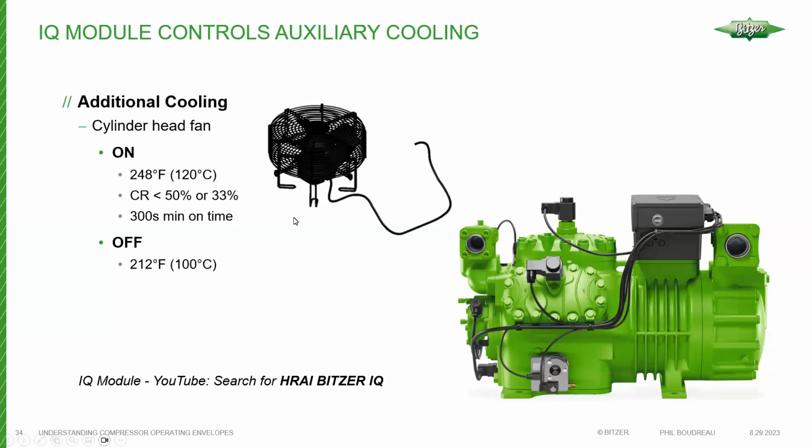And you could, in theory, have a temperature sensor there, and you can control it that way as well. But that's not typical, at least here in areas where I've seen equipment operating. Generally, it has been an auxiliary contact used to do that, or even sometimes just a control relay. They'll use that to energize the head cooling fan.